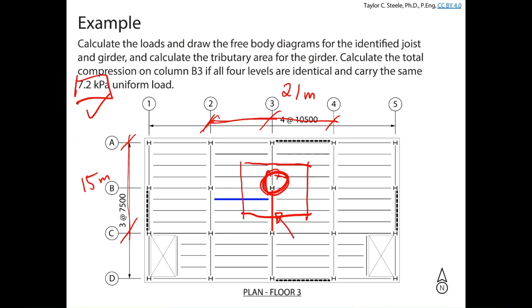All of these joists, they have the same spacing and they have the same load. So the joist loads and the problem, if you solve the blue one, you're solving essentially all of the other joists, except perhaps these 3 shorter ones down here, and except perhaps the ones on the outside of the building. And so once you know the loads on one joist, you know the loads on almost all of your joists. How about the girders? What's going to change for your girders? Is the problem we set up for the red girder going to change substantially for the rest?